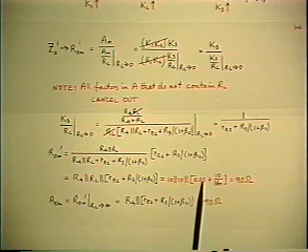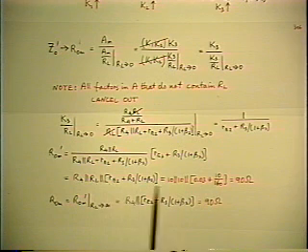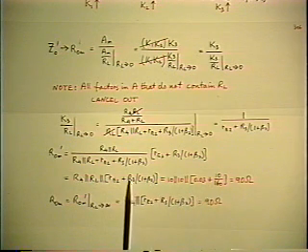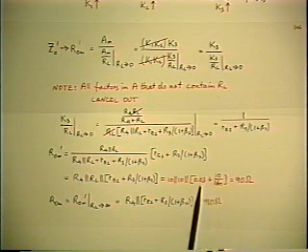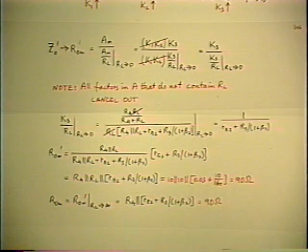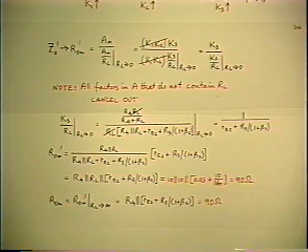When you substitute numbers, R4 is 10K, RL is 10K, the RE2 is 30 ohms, the reflected R3 is 60 ohms. Add the two together, you get 90 ohms in parallel with 5K. The 5K doesn't do anything, and you're left with the 90 ohms.